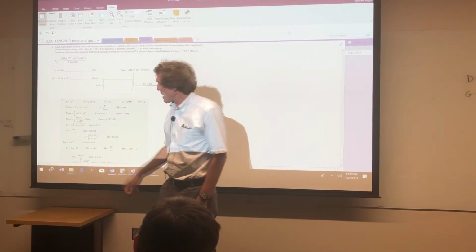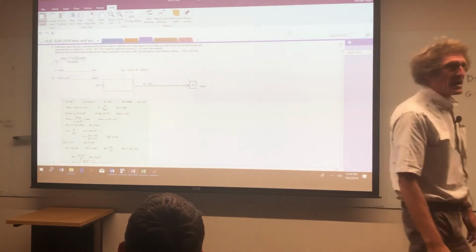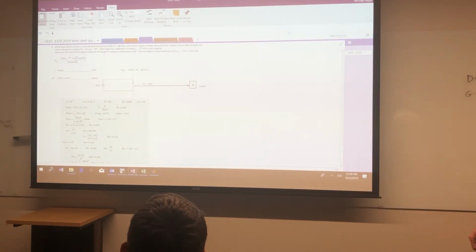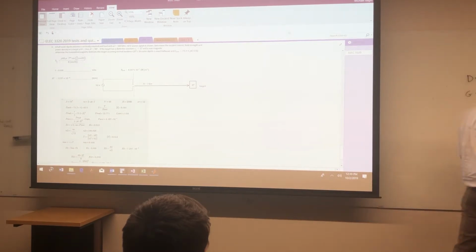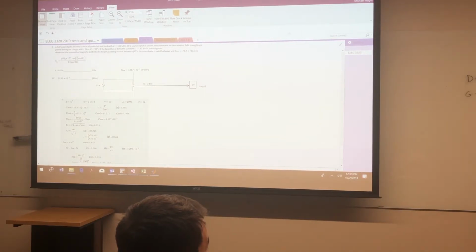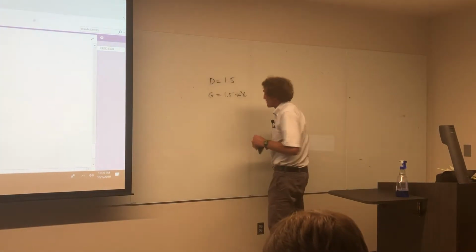I know the radiated power is just 1/2 that resistance, the antenna resistance, times I squared, right? Magnitude of I squared, right? That's the total radiated power. Follow me? Once you have the total radiated power, if you want the actual power density anywhere, you didn't have to do it this way. You can just use the E field equation, all right? You didn't, but this is straightforward to me.